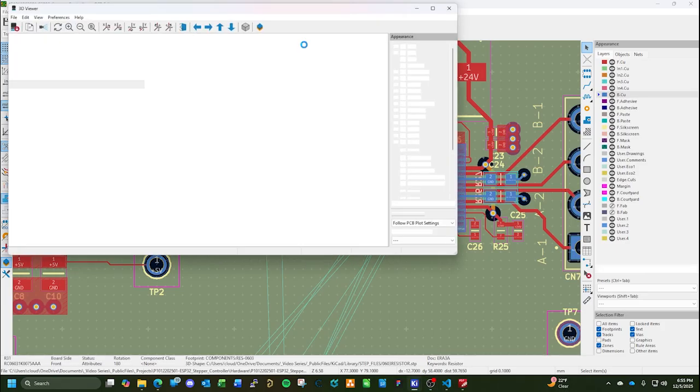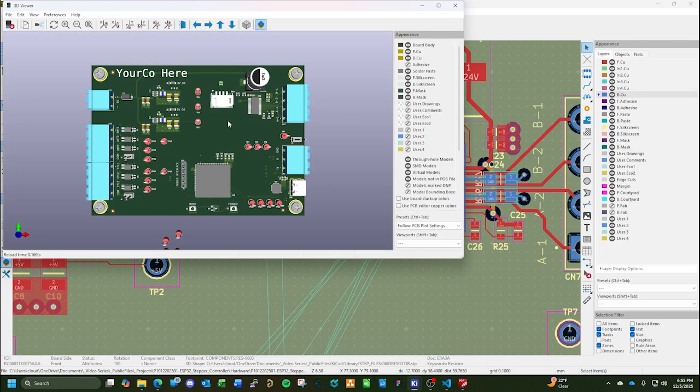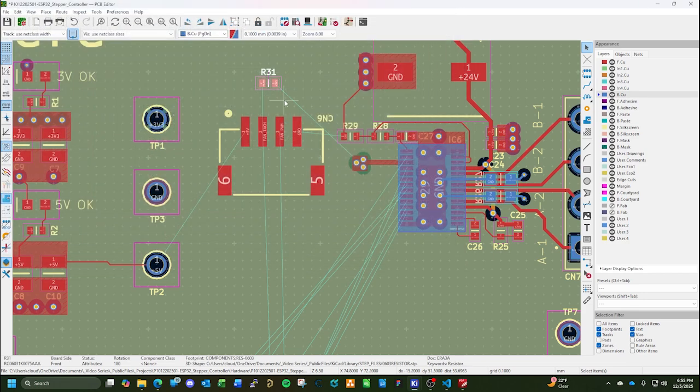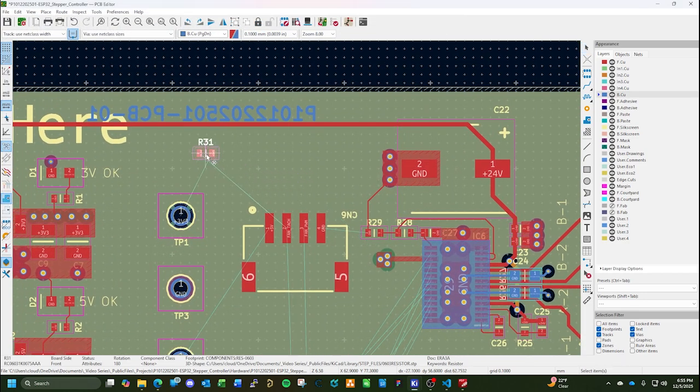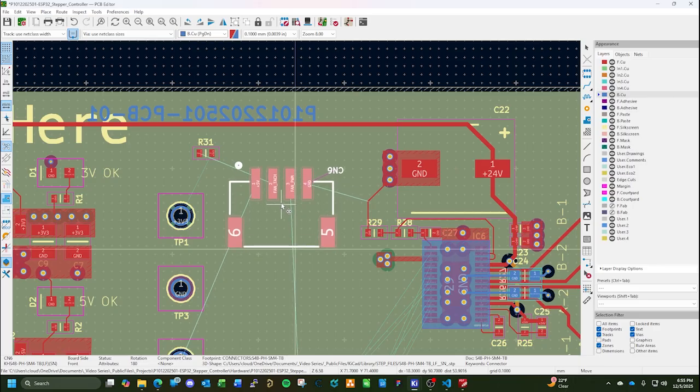Let's just take a gander at the 3D view. Would be more acceptable, I think. Maybe we can push a little further up and over this way, a hair, by these test points. Put the resistor, so let's move you up a little bit further, because I also want to make sure I don't interfere with the heat sink that's going to be strapped to that guy.